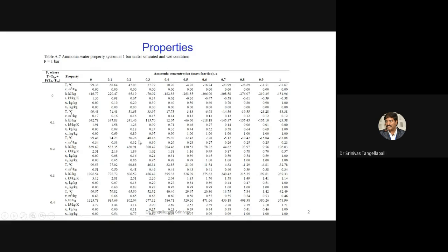So this is, I can say, the liquid vapor mixture. In this liquid vapor mixture, we may refer to what properties we can see: the specific volume v, enthalpy h, and s is entropy. Concentration is in small letters. I will open the PDF files. I will show. And the concentration of liquid, concentration of vapor, and temperature. See, the temperature is variable in the liquid vapor mixture. Once you keep on adding the heat, the phase change takes place at variable temperature.